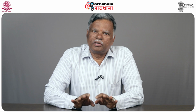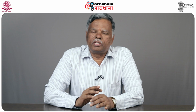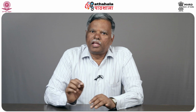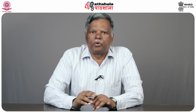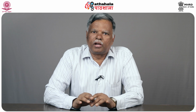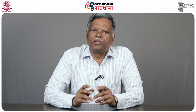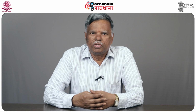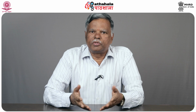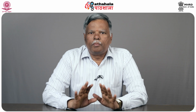Now on the Smith chart, along the right radius OB, we have the location of Vmax whenever there is VSWR rho, and at the location of 1 upon rho, that is the reciprocal of VSWR, we have Vmin. Vmax and Vmin locations are very important and they are used in many calculations for finding the values of reflection coefficient, transmission coefficient and so many other quantities. So let us see something about this.